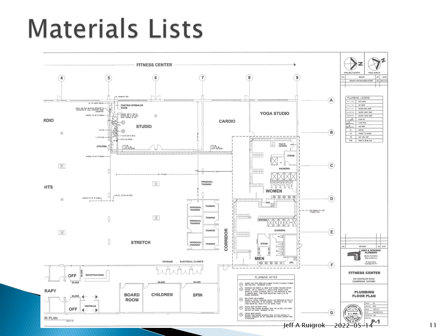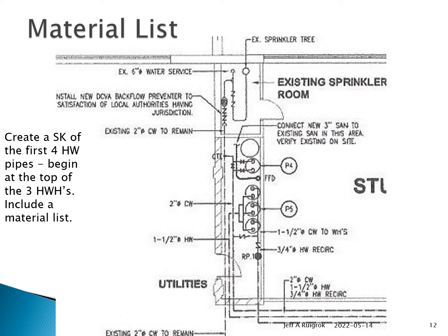Let's take a look and see. For this one here, this is the room, the mechanical room at the front of the building. I believe it would be the west wall, where that verify and field note was. And for this drawing, I'm not going to do it here, but I would ask that you draw this piping for the hot water heaters. And keep in mind that the water heaters sit up off the floor, and they have what's called an equal draw, equal feed assembly, at least on the hot water side.